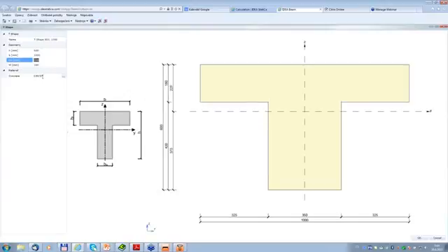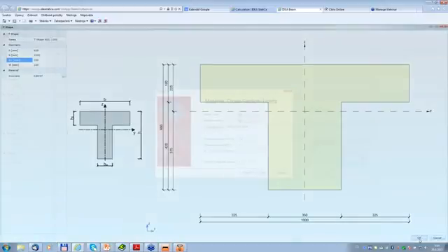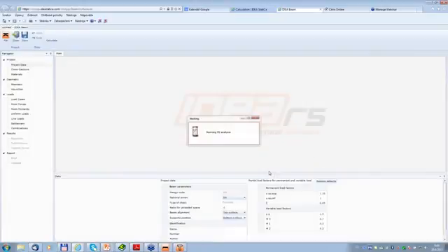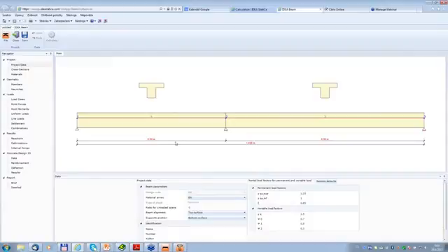This is a real example, concrete C30/37, real example of the beam in the design of one wine cellar, which is in South Moravia in our country. Permanent load in that case was minus 20 and variable load minus 5. I want the program to generate the critical load patterns with zero load on unloaded spans. Now I finish and my beam is generated using that wizard.